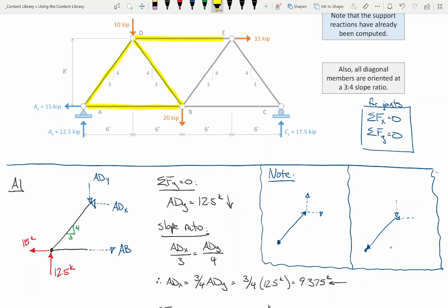Now, I'll say this. Joint C is probably easier because there's less bookkeeping, but part of the challenge with truss analysis is that you are going to have to do bookkeeping whether you like it or not. So I would rather nosedive into that. Let's do one that's going to have a lot of arrows in a lot of different directions to make sure that we're comfortable with it. Let's do joint B. There's 4 members going through it.